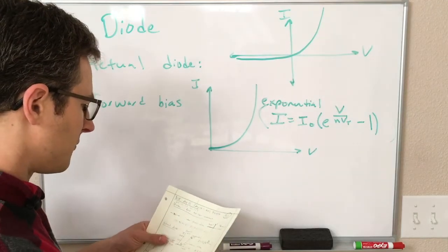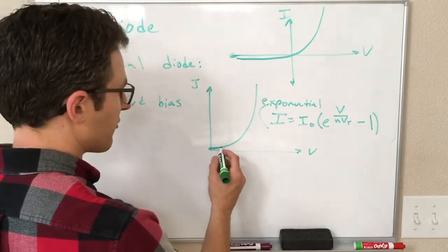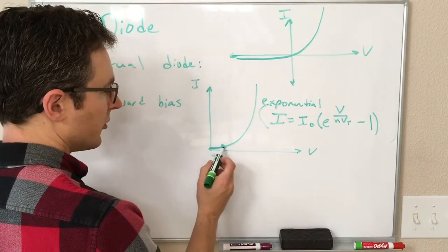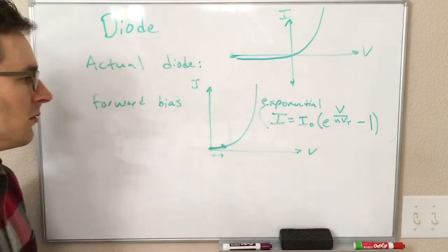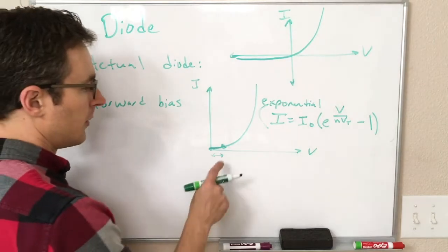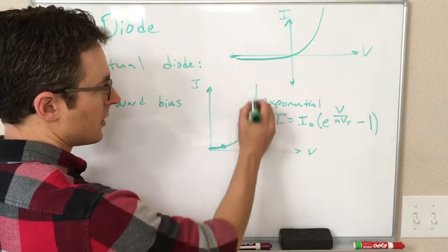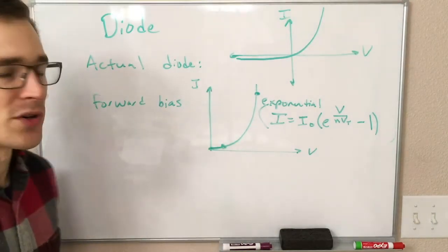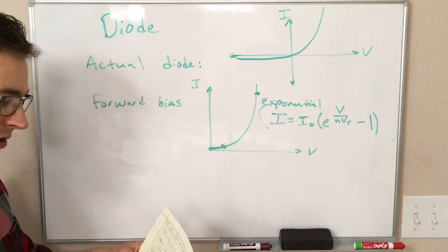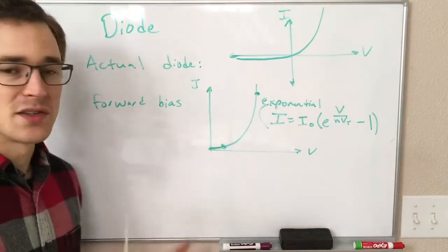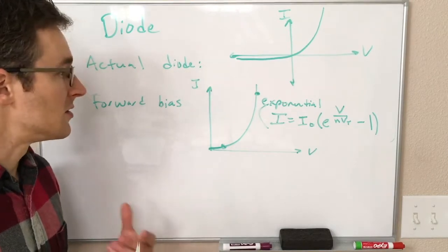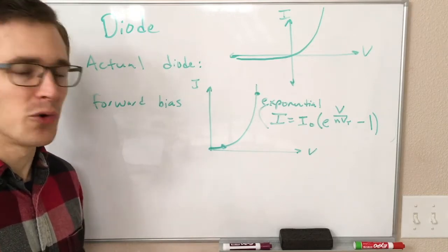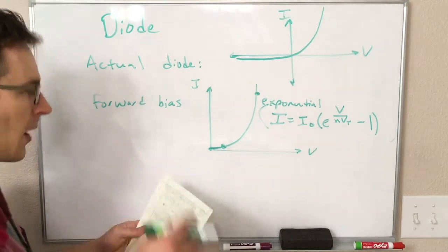Okay, so at 2 different points on this graph, let's just look at a point down here. Down here, we have some small voltage and very little current flowing, right? If we increase our voltage to, say, here, we definitely have an increase in voltage, but we have a much larger, proportionally a much larger increase in current. And that is what we mean when we say this is nonlinear. Doubling the voltage does not double the current the way it does for resistors and capacitors and inductors, for DC and AC circuits.